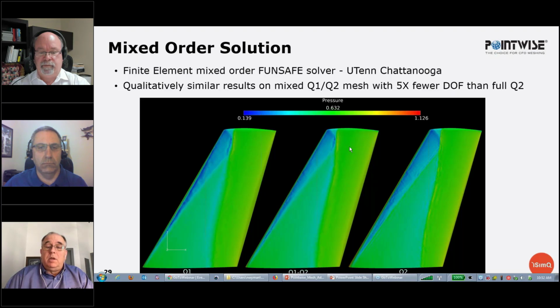What we've been describing here is what's normally termed a feature-based adaptation scheme. If you have an adjoint solver, an output-based solver, then you can actually introduce the sensitivity of the mesh through the adjoint output variables and have it converge to the proper mesh in a consistent manner. If you pick the wrong adaptation sensor, then you may be driving it to the wrong mesh. So it's really important which adaptation sensor you pick. That's a very, very good point.